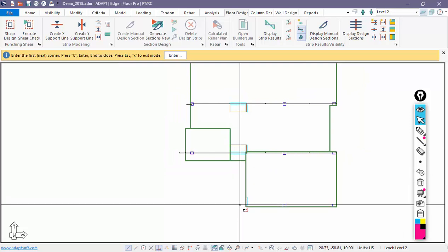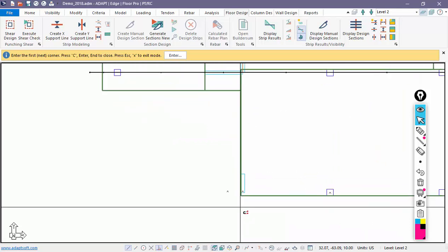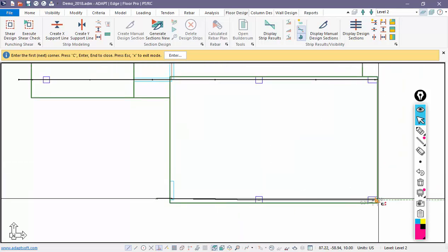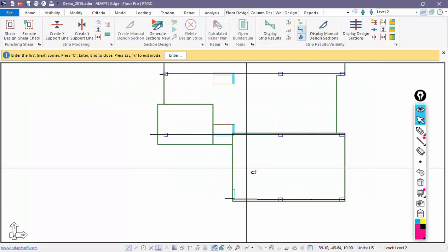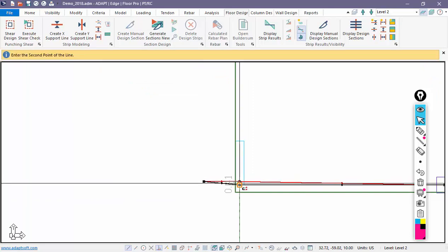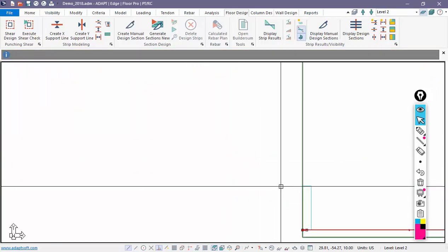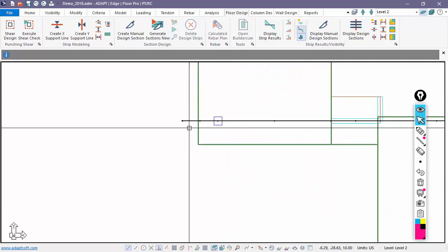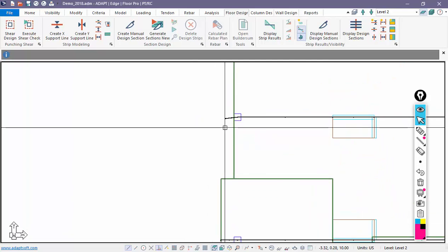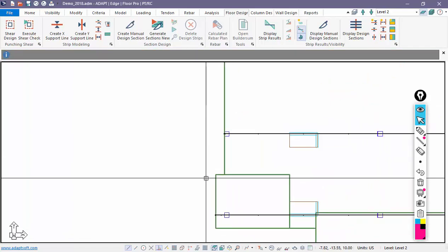and over here we'll do the same. We have wall. Here the wall's oriented differently, so we'll just snap on the center of that wall and then enter. Now if you wanted to move a point, I can move a point. I could take this and move it down, and then these points I'm actually going to just close them back off at the slab edge. Again, the functionality here has been improved for version 2019, which should be released September of 2019.